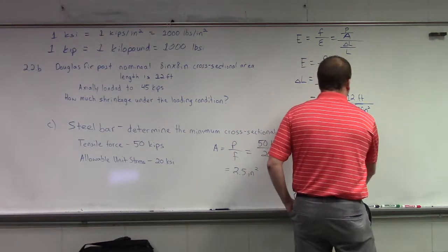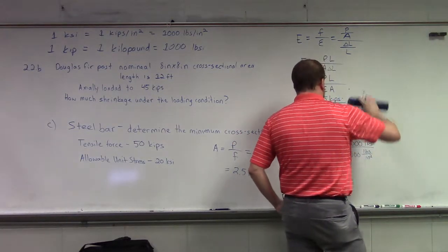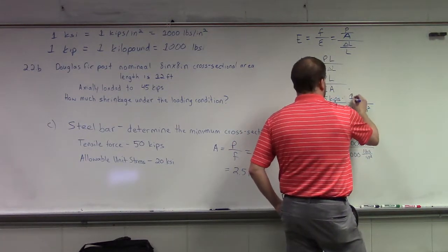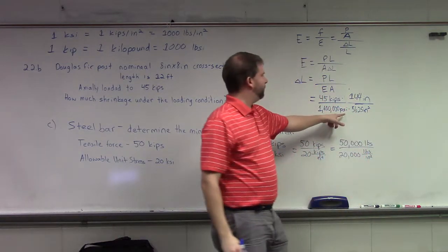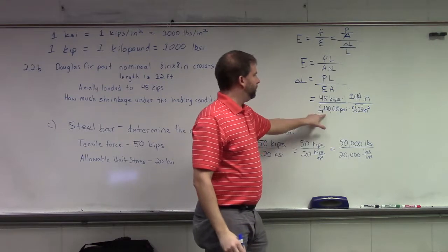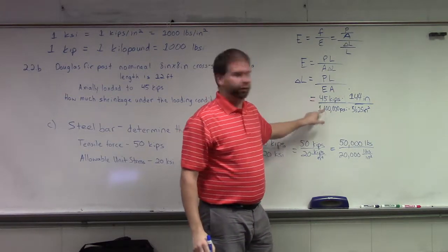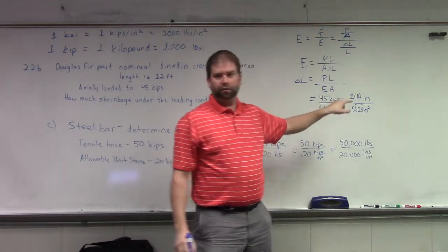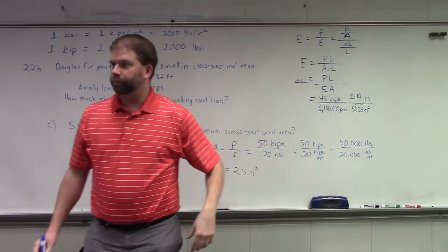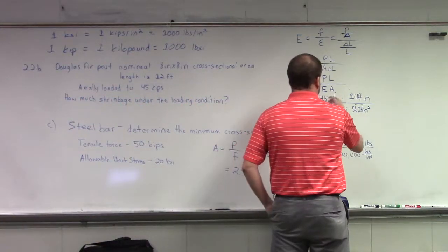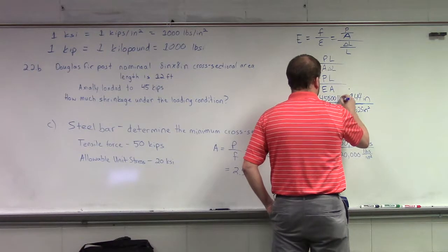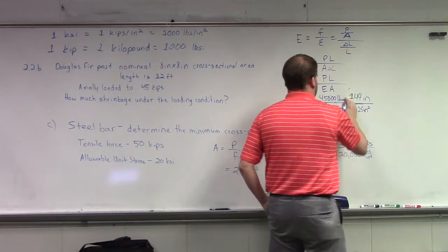Okay, so a couple things. We said this will be 144 inches, right? We'll change that because we're in square inches and PSI down here. What do we want to do with these? We have PSI here, we have kips here, so it goes to pounds. Convert to 45,000 pounds.